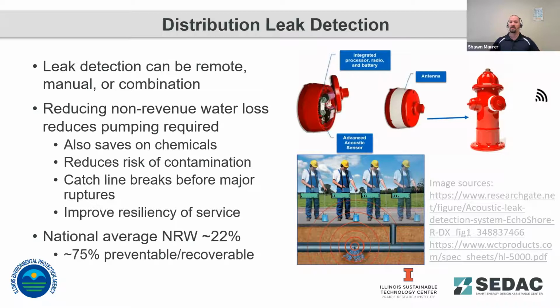But again, focusing on a lot of plant energy being tied up in pumping, if we can reduce that pumping energy, how much water we're moving, we're going to see savings. Distribution networks are buried under the ground, out of sight, out of mind. So when leaks happen, we don't necessarily know they're there. A few gallons per minute can be thousands of gallons a month, tens of thousands of gallons per year.